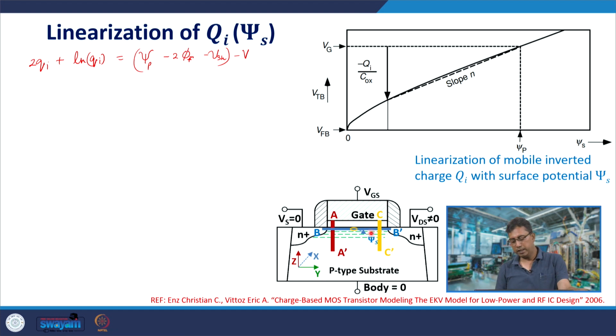As you keep on increasing V, we had seen in our previous lectures that the inversion charge density keeps on reducing, and it would attain such a small value that it has a large negative exponent, and therefore this term dominates over the other term, and that is how you find the right hand side to be negative. So, there is a value of local channel potential V for which the left hand side becomes 0, is it not?